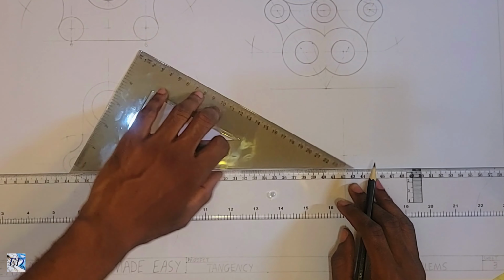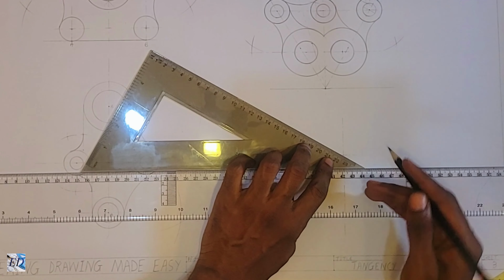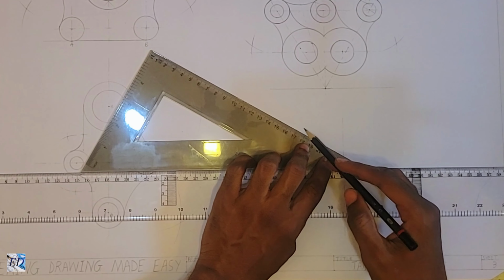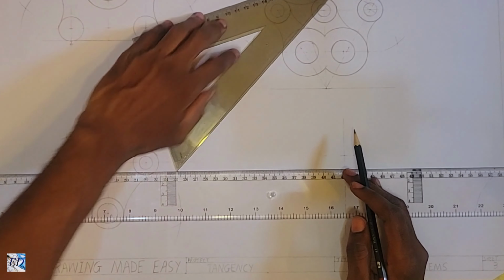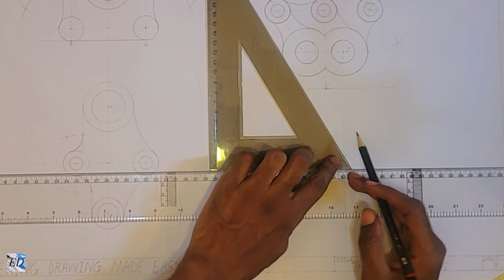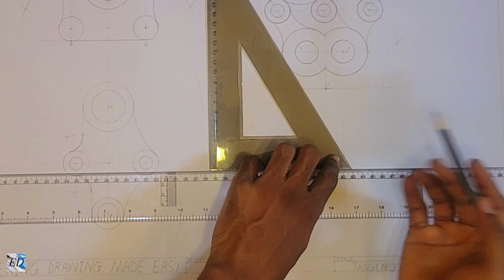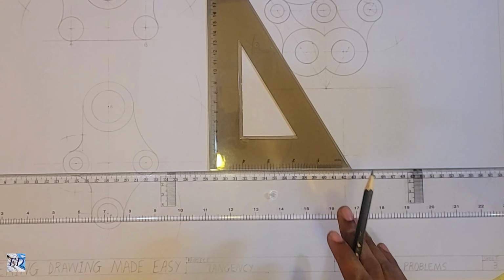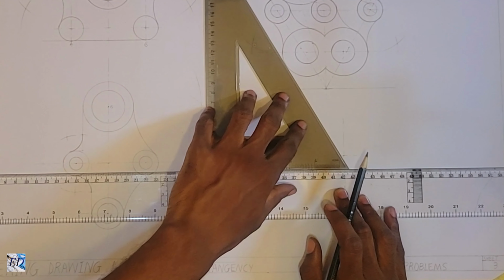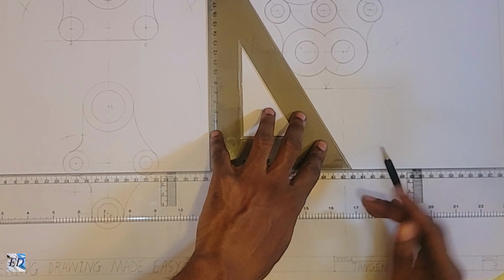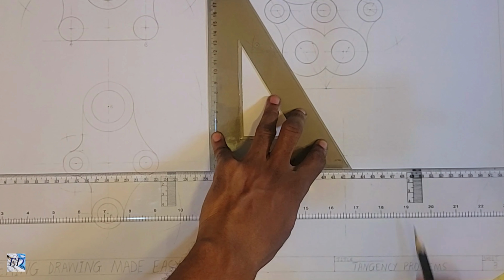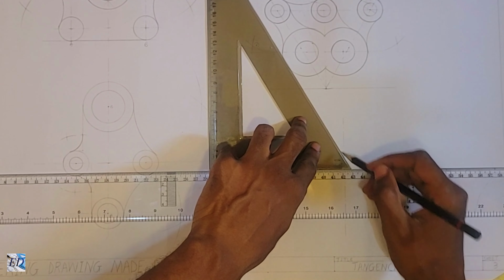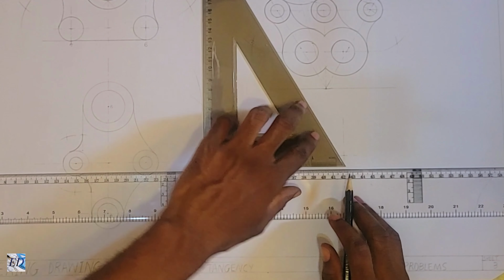If you turn it this way rather, and then you draw the line, the angle from here to here is going to be 60. But if you turn it this way, the angle from here to here will give you 30. So that is one way to go about it. You have to understand how to use the tool very well. You draw the line, and then you have your 30 degrees from this line.